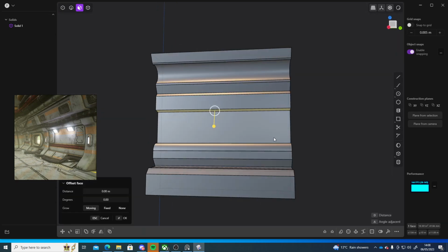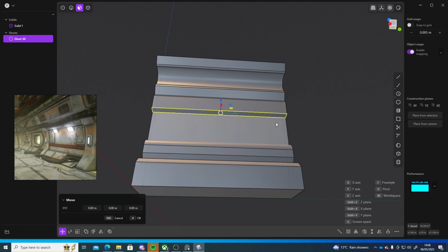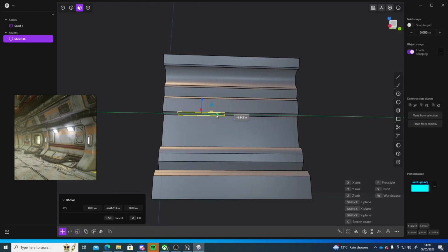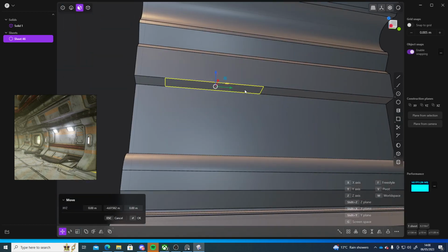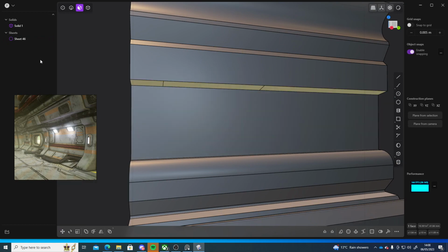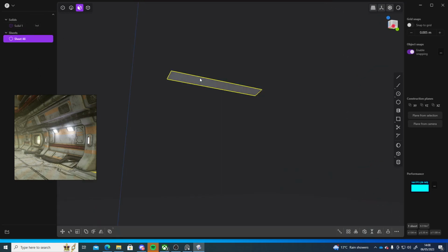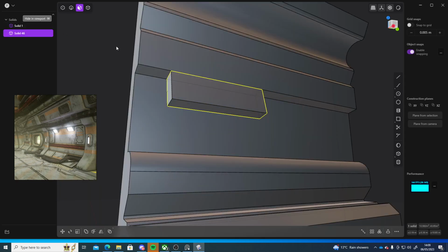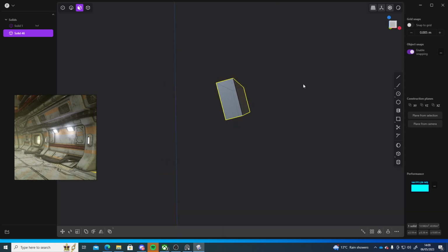So what I'll do is I'll grab this face here. I'm going to press Shift D to duplicate it. I'm going to press S to scale. I'm going to scale it down. I'm going to press G and move it over to the side here. Press three to go into face mode, select it, and select that sheet. Let me just hide that top one. There we go. Oh, E. There we go. Unhide that. That's going to do that sort of thing. That's fine.